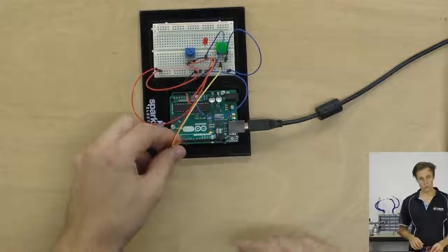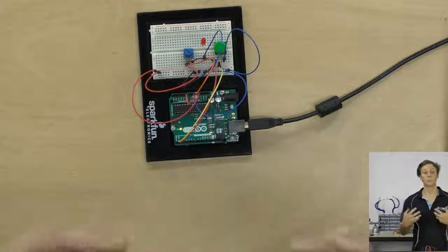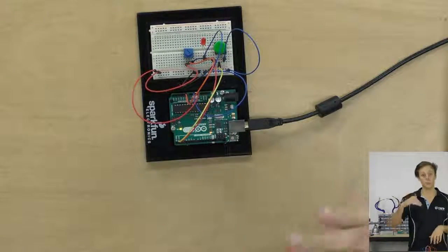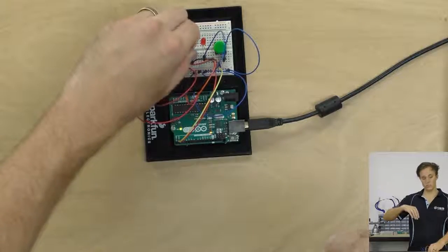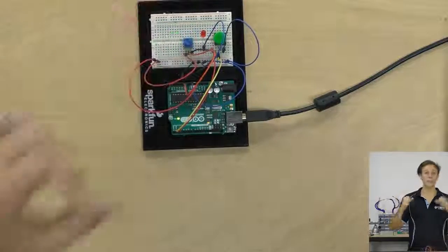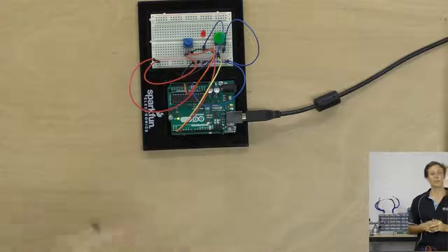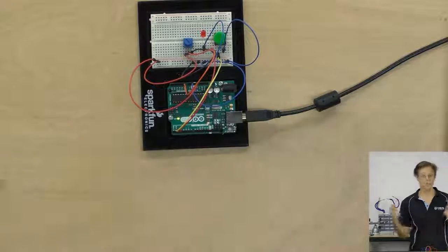If, for example, you tried to connect the LED to a non-hardware PWM functional pin and tried to use analog write, it would simply turn off when you turn the potentiometer, and then when it gets to about halfway, it would turn on, because it's only capable of ones or zeros. Again, you can use software PWM, but that's a little bit beyond the scope of this section.